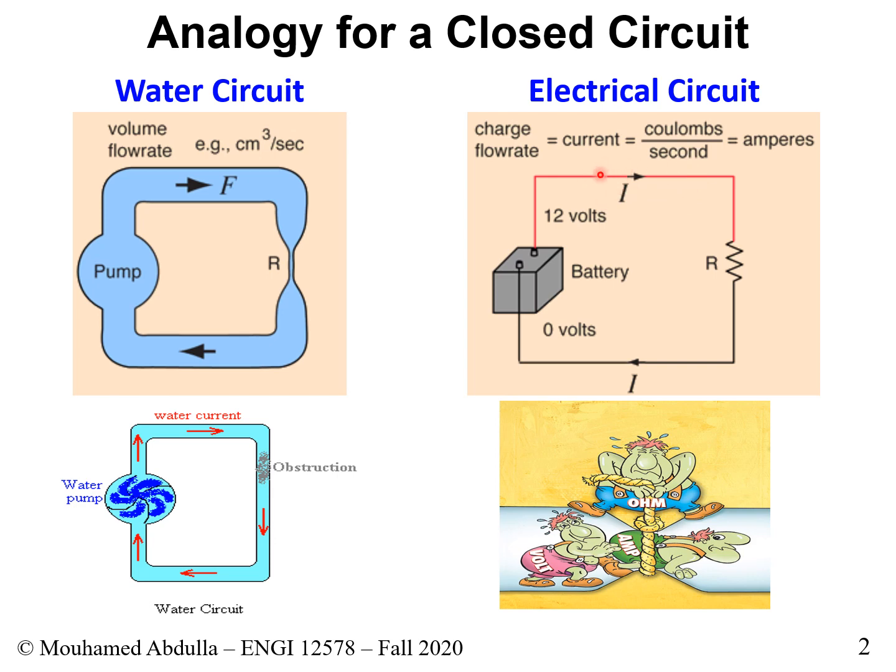When you make an opening, you let the current flow in through your DMM, your digital multimeter, and that's how you measure current. So current is always through, and voltage is always across, and that's kind of what we wanted to show you here.